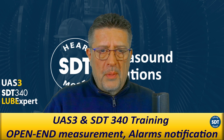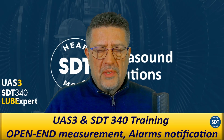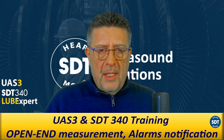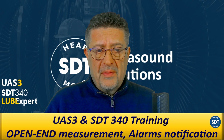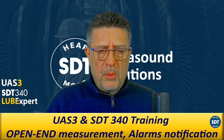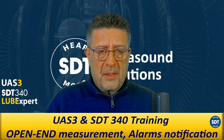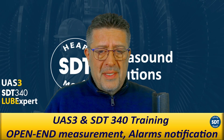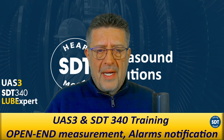As you know, all the measurements need to be set in UAS3 or set in SDT340 in a free mode, and the acquisition time is defined, whether it will be 5 seconds, 7, 10 seconds or 10 minutes, which is the maximum measurement time in SDT340 at 32 kilosamples per second. So there are still situations when we cannot define nicely the acquisition time.